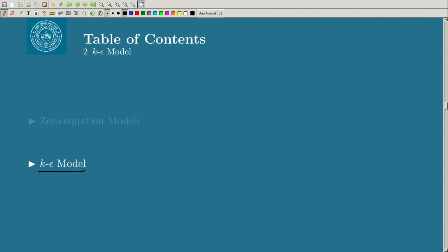So, there are so many K epsilon models. A few are like standard K epsilon, which is popular, and then you have RNG, and then you have realizable, and these are basically the eddy viscosity models. Then you have this cubic K epsilon also, but this is not just eddy viscosity, this is a non-linear eddy viscosity model. Okay. So, here the viscosity is not only linearly dependent on the velocity gradient, but it may also depend quadratically or even on higher powers of the velocity gradient.